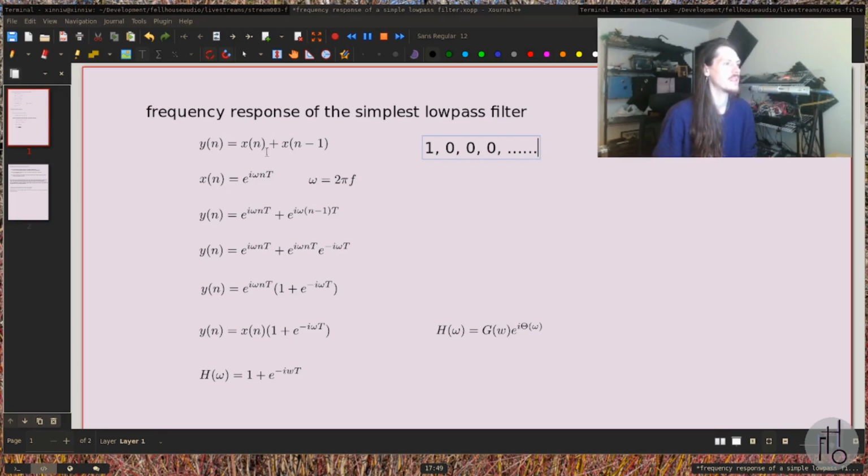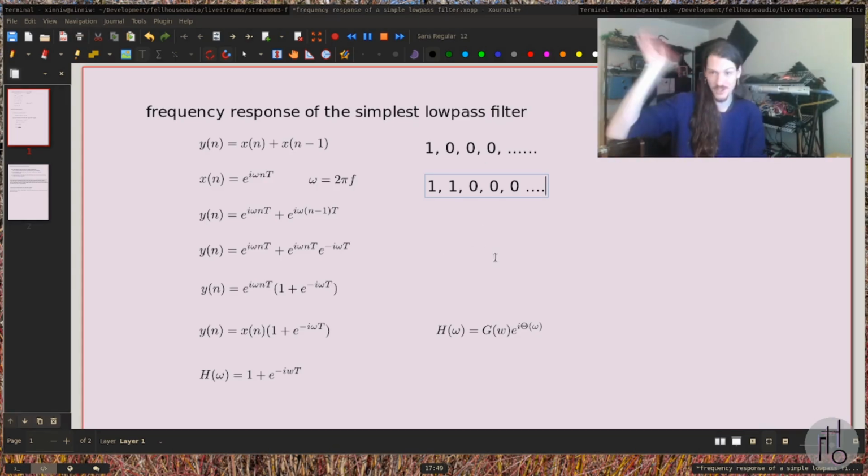And then we would get 0 plus 1 is equal to 1. Actually, write these out. And then we would get 0 plus 0 is equal to 0. And then it's all zeros from there. So this second list that we wrote is the impulse response. It's the output of the filter when it's fed an impulse. And we can see it is very finite. It doesn't last very long. It's just 2 samples of information, and then it's all zeros.